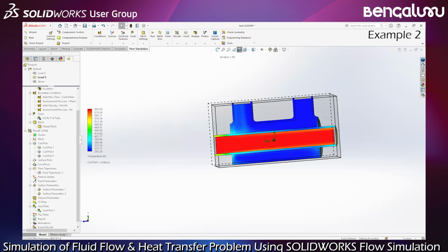The geometry recognition is very powerful with flow simulation and with the check tool, etc. Of course, if you have some CAD errors or some gaps or leaks, clearance, it could make things complicated, but you have some SolidWorks tools to repair before going to flow simulation.